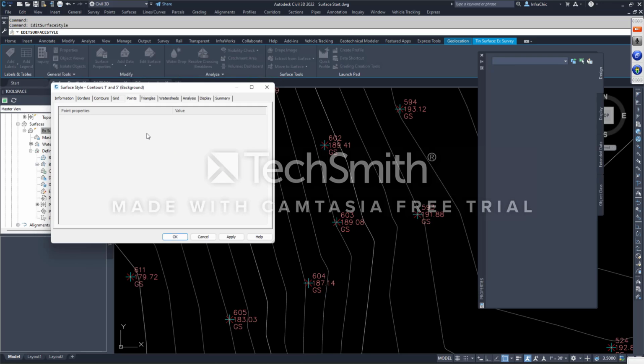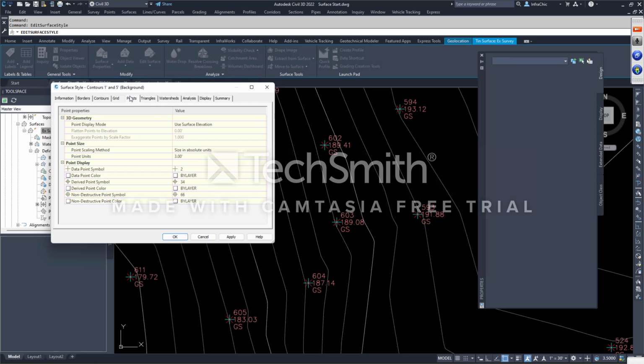Again, right-click, select surface, right-click, edit surface style, and going back to points. Points can look different. On the points tab of the surface style dialog, you can set them to be in absolute units. You can set the look of what they are to different objects by clicking on the point object and then clicking on the More button. And what option do you want? Maybe I want that. Okay. There is a data point. These are data points, a non-destructive point symbol. These are points along the boundary edge. And a derived point: that's a point between 2 points, an intermediate point that it figured out on its own but is not really a survey point. It'll be represented by a circle and a dot.